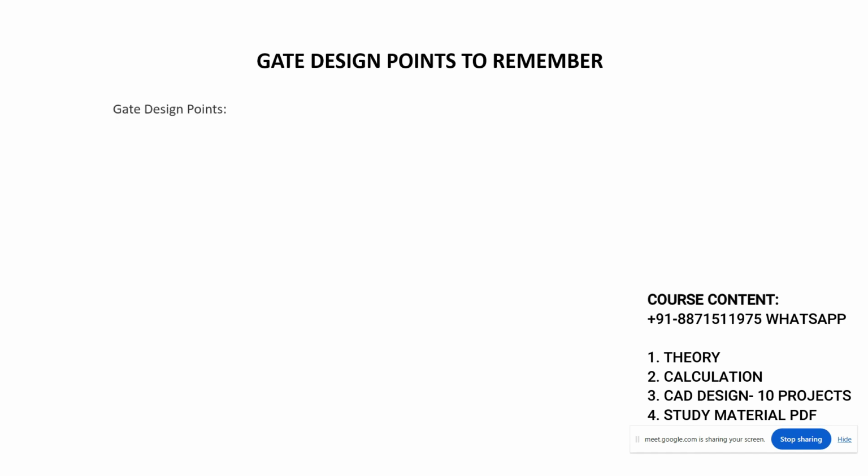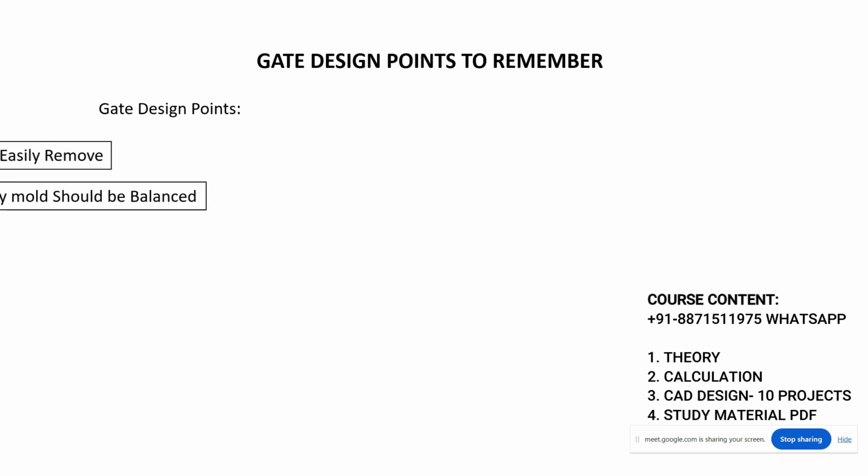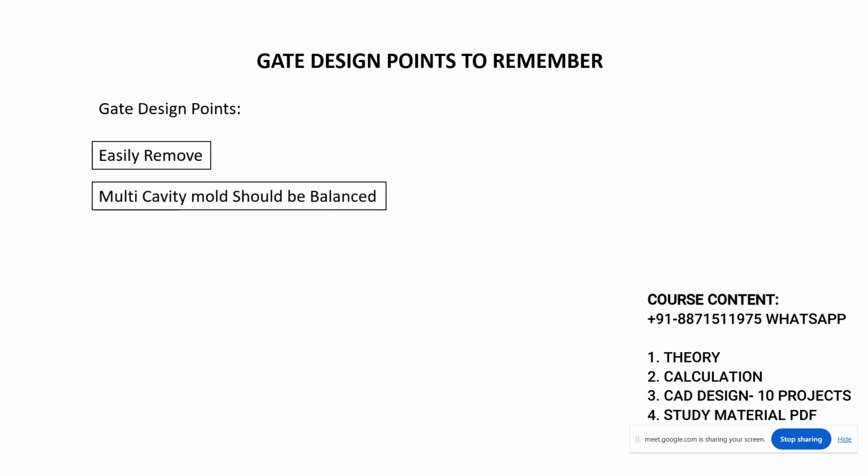Gate design points to remember. See here, for example, gate design points. If we are designing a gate, it should be easily removed first, and second, a multi-cavity mold should be balanced. If we are dealing with multi-cavity like 2, 4, 6 or 8 components, it should be balanced.